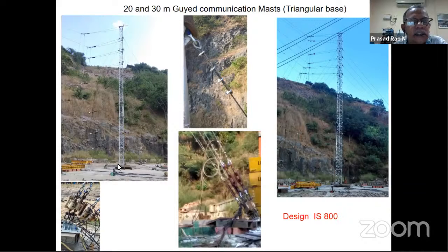There we can use this tower, whose base width is only 400 mm, a 400 mm triangle, and height is around 30 meters. And we have measured all the guy forces using a load cell attached to a control system, a real-time digital control system. And you can see all calculated horizontal loads are applied to the structure, and full-scale testing was done.